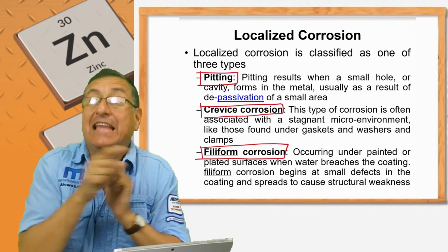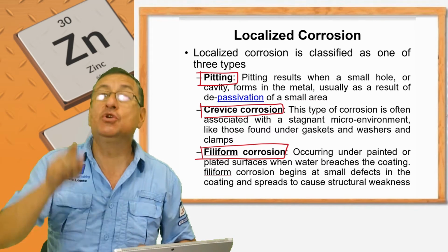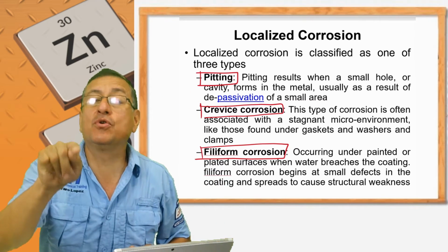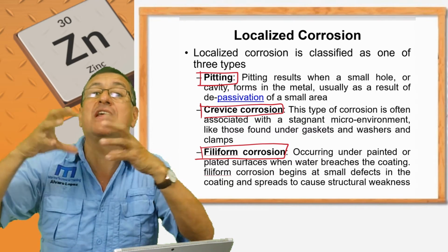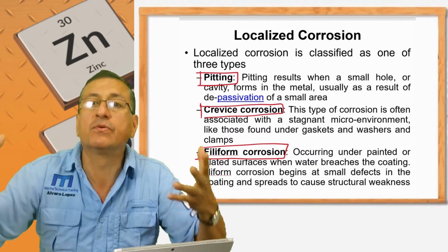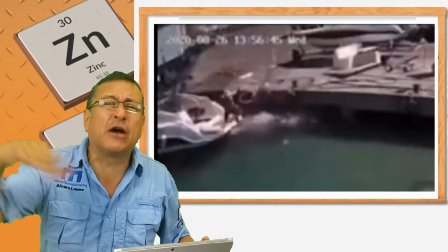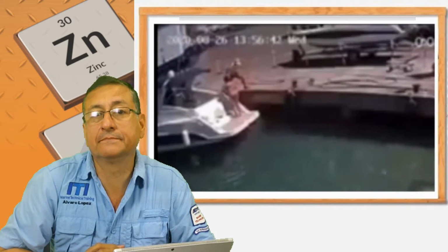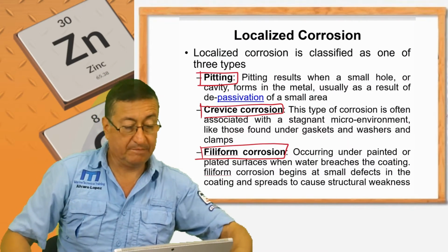And additionally, that start motor, that alternator, is not ignition protected. Your boat is a gasoline boat. The engine room is closed and your motors are carbureted. In your engine room, you have a lot of gasoline vapor, gasoline fumes. And you have start motors and alternators that are not marine grade. Okay? Is it clear? I hope you are clear with those concepts.